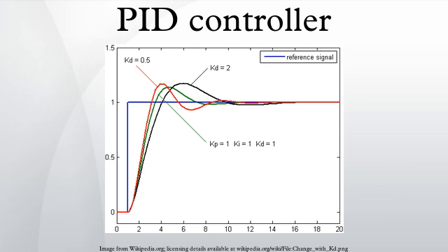Setpoint step change. The proportional and derivative terms can produce excessive movement in the output when a system is subjected to an instantaneous step increase in the error, such as a large set point change. In the case of the derivative term, this is due to taking the derivative of the error, which is very large in the case of an instantaneous step change. As a result, some PID algorithms incorporate some of the following modifications: